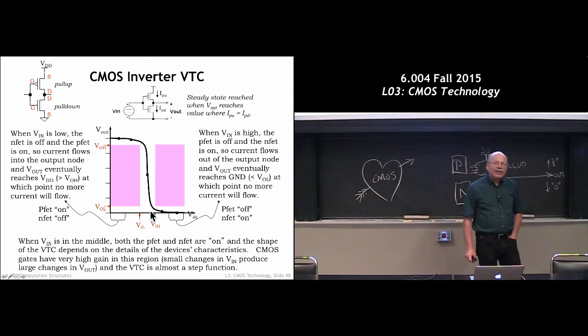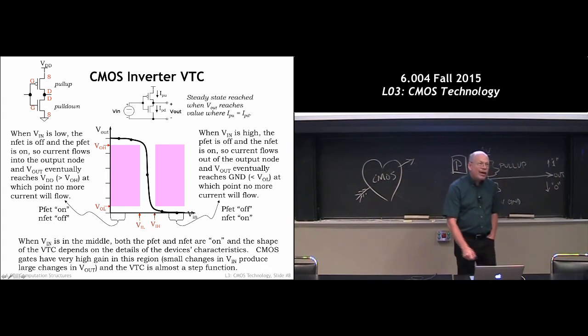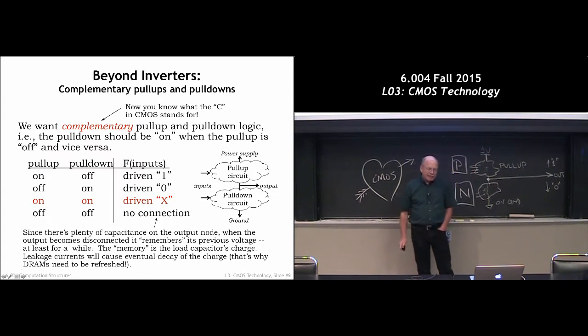In fact, sometimes in 111, which is the Introduction to Digital Systems lab, people wire up their logic circuits backwards, and all of a sudden you start seeing these plastic packages bubbling, and they go, "Wow!" And you go, "Yeah, don't touch it." And they say, "I didn't realize it conducted that much current." And I said, "Well, not for long." So short circuits are a really bad idea on pretty much every front. So we avoid those in our basic design.